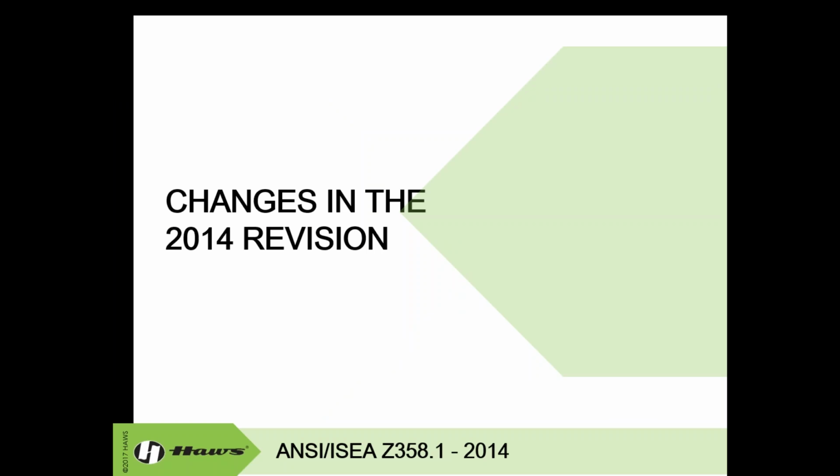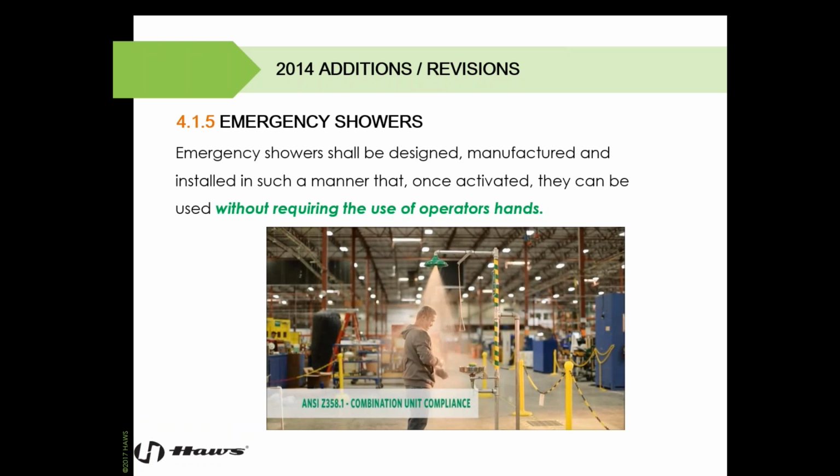Let's move into some of the changes that we earlier went through in the last 2014 revision. This one specifically is really just a verbiage change. It was to help strengthen the importance of the hands-free operation to allow the victim to remove clothes and hold open the eyes. I guess I should change the slide for you. Emergency showers shall be designed, manufactured, and installed in such a manner that once activated, they can be used without requiring the use of the operator's hands.